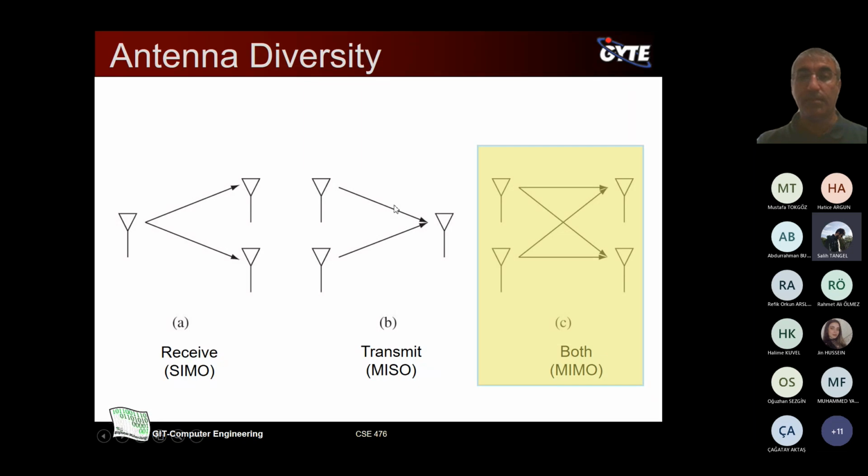Yes, it's more clear. So the receiver and the sender are just phones, and the middle ones are base stations. Yeah, actually this technology can be utilized, but when it comes to practice, because of the size limitation, SIMO is used in the mobile devices, and MISO is used in the base station. There are some cases where we use MIMO as well, but these are not mobile devices, more like military applications.